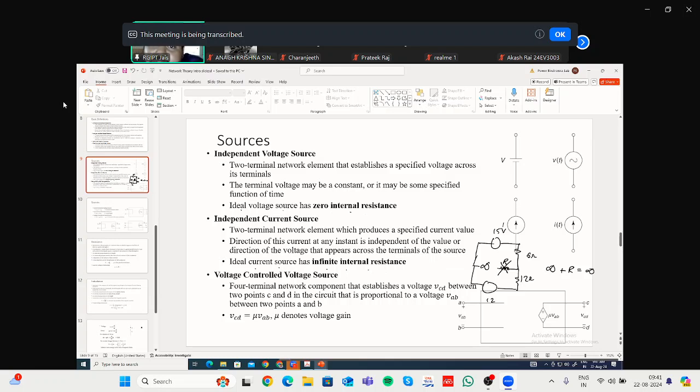Similarly, if you consider a voltage source, you can ask me the same question when we study nodal analysis. There will also be a concept called supernode and everything. So you may ask, what happens if we apply a resistance in parallel to the voltage source? If we apply a resistance in parallel to the voltage source, what is the resistance of this voltage source? It is 0. That means in terms of resistance, this is closed.